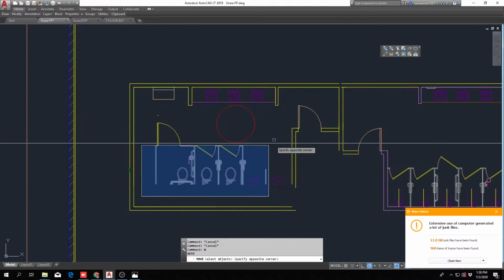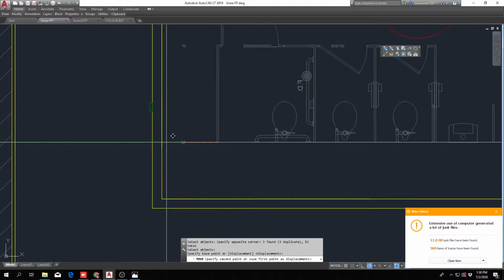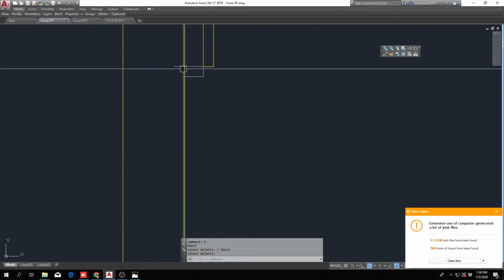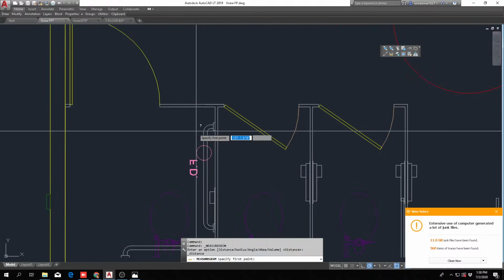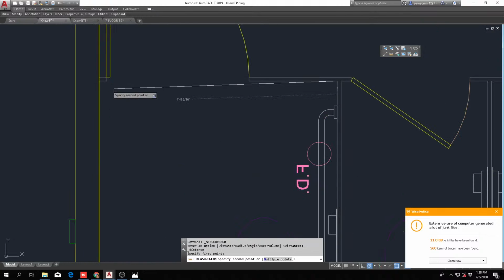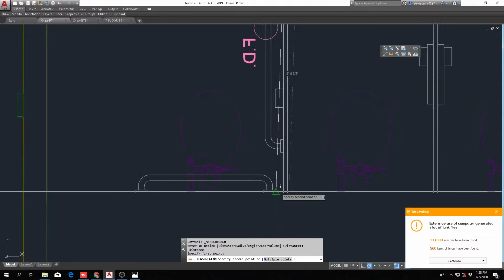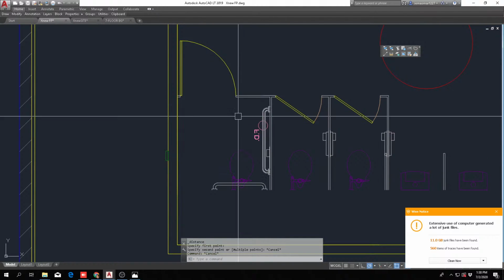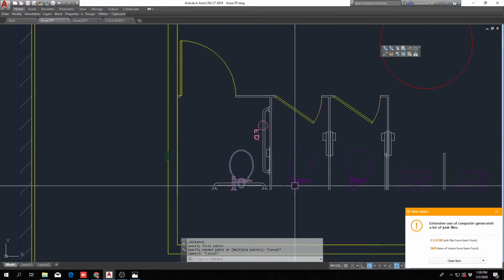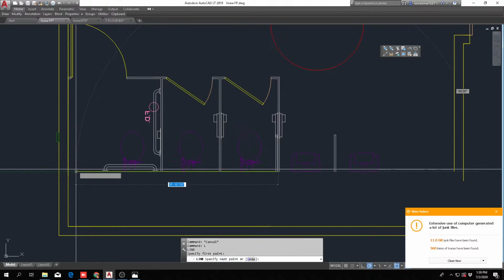Another thing is, you notice I took off one of the toilets, and I'm gonna put the stall over here because I want to make the restroom smaller. The rule of thumb for the toilet partitions is, if you have 5 feet inside for the handicap, that's also gonna work for what you need to draw.